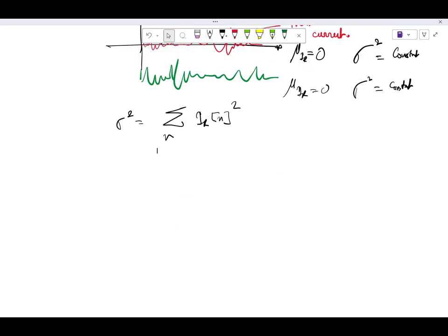Now, if we take the same resistor and do a frequency domain experiment, that is, I take this resistor and, instead of putting it in an oscilloscope, I put it in a spectrum analyzer. Now, what is a spectrum analyzer? A spectrum analyzer is nothing but a band pass filter with an extremely narrow pass band, whose output is the power that passes through that band pass filter. It's basically a power meter across a very small frequency range.